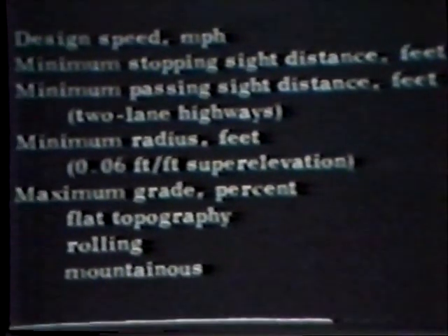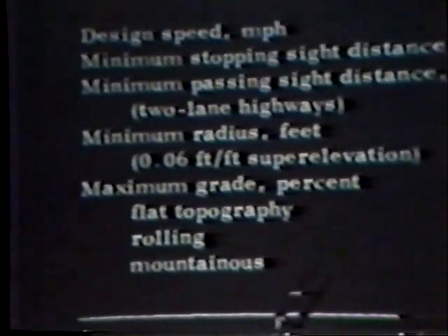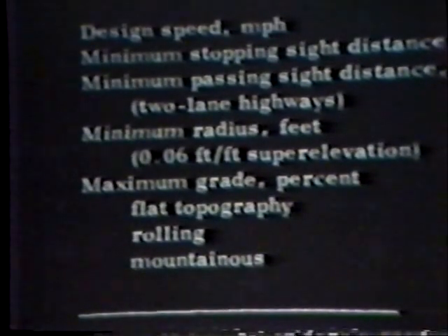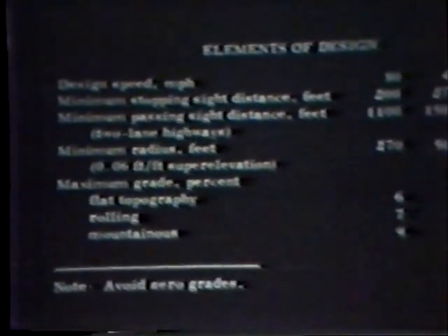We try to avoid zero grades for drainage purposes. And all of these kinds of things are available in design standards which are published by agencies such as the American Association of State Highway and Transportation Officials.